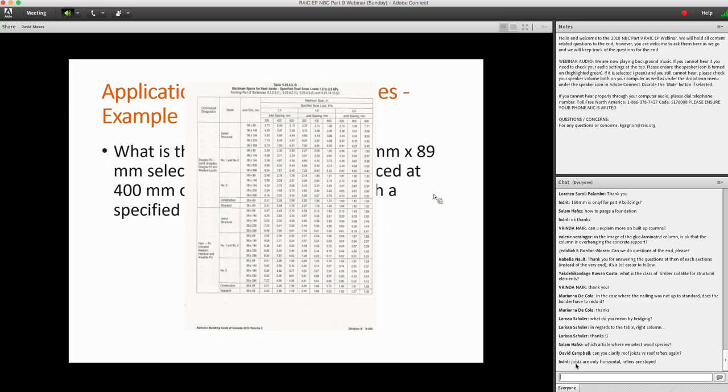So if you go in the table, you'll see, and I'm going to tell you which page number this one came off. This is page 455. And on this page, we see Douglas fir is the grade on the left, and down below it is hem-fir. And the flip side of that same page is spruce and then the northern species. So that's where you can select off the grade of the species that you're going to be building with. So if I'm in Ontario, I'm pretty certain that most of my builders will want to be using spruce. So that'll be on the next page over.